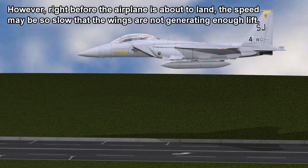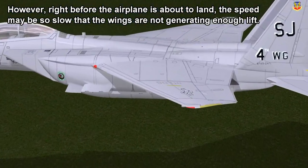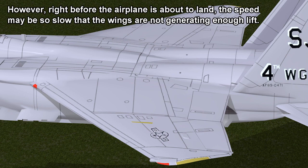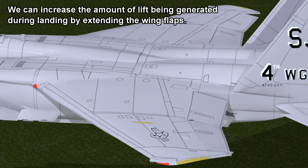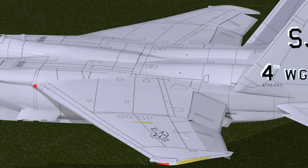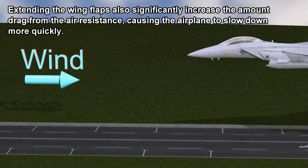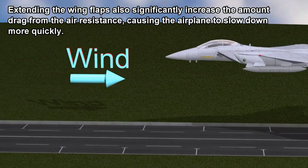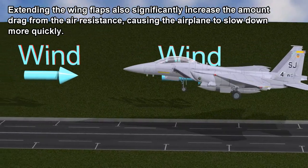However, right before the airplane is about to land, the speed may be so slow that the wings are not generating enough lift. We can increase the amount of lift being generated during landing by extending the wing flaps. Extending the wing flaps also significantly increases the amount of drag from the air resistance, causing the airplane to slow down more quickly.